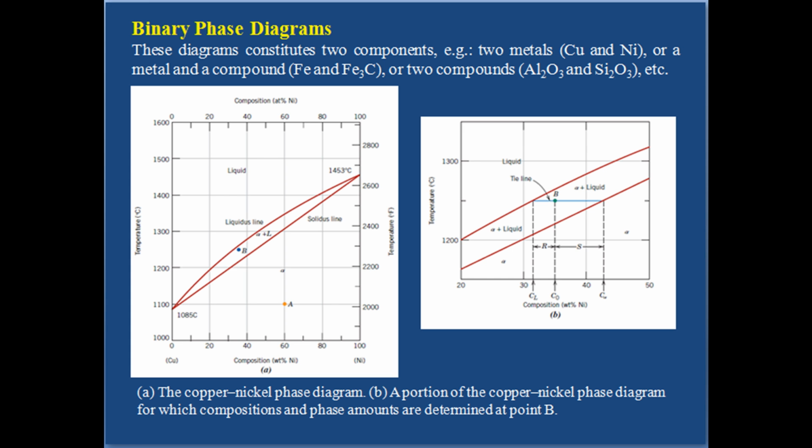The crystal structure of each element of the solid solution must be the same. The size of the atoms of the two elements must not differ by more than 15%. Elements should not form a compound with each other, that is, there should be no appreciable difference in the electronegativities of the two elements. Elements should have the same valence. All the Hume-Rothery rules are not always applicable for all pairs of elements which show complete solid solubility.